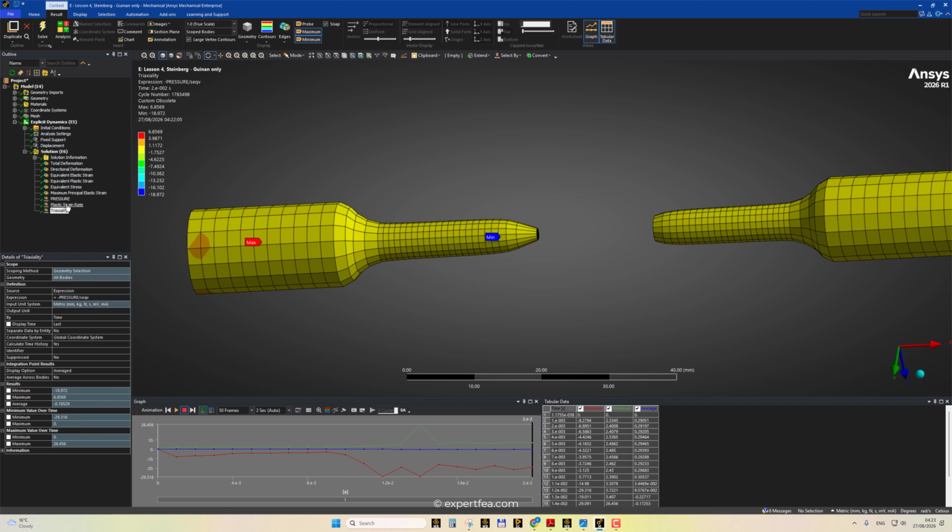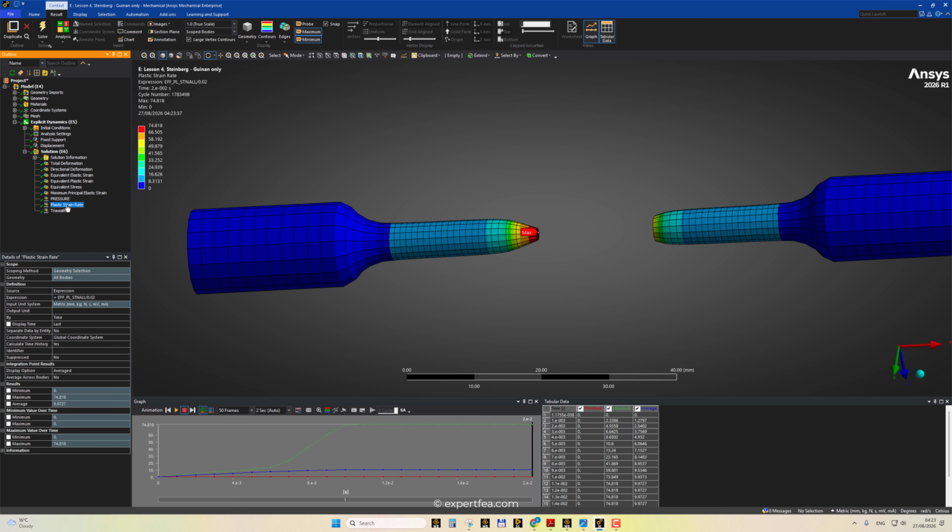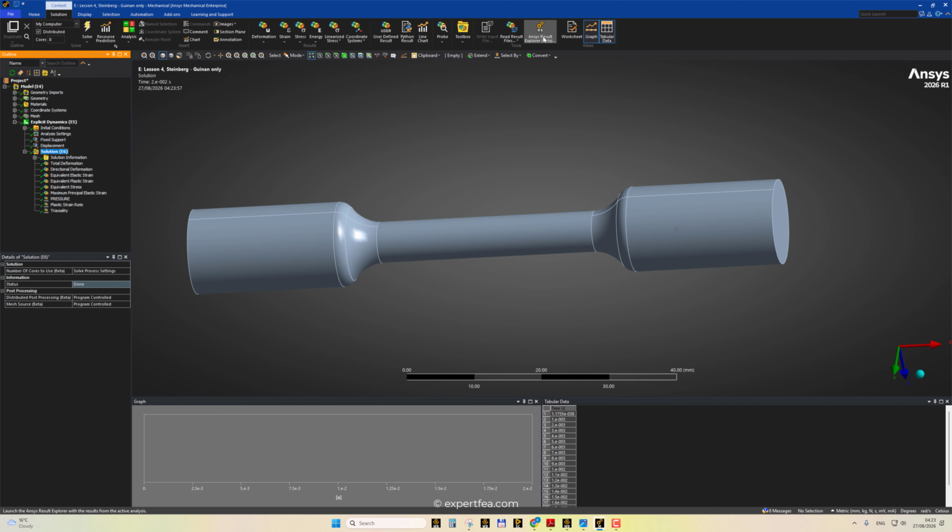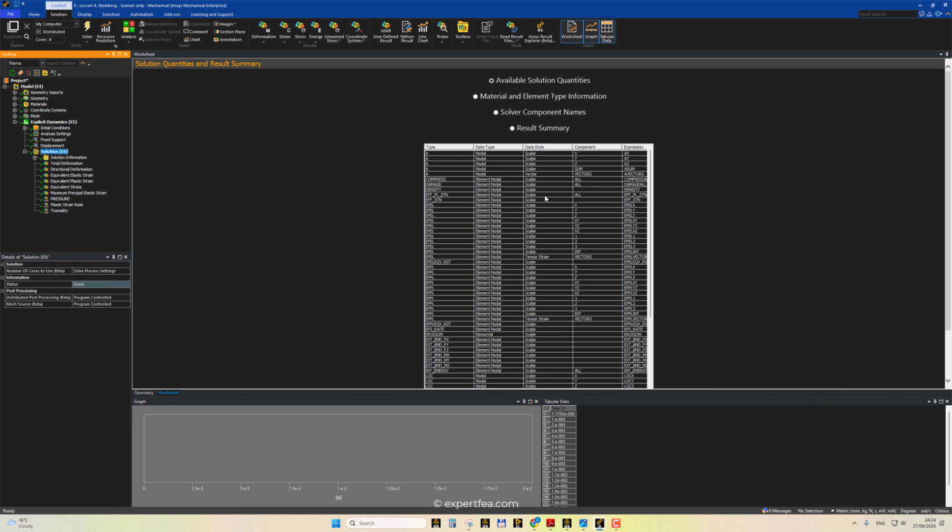I was talking about triaxiality, and now we do see some plastic strain. This is a rate that I calculated, like a speed for the internal deformation. In reality it's effective plastic strain divided by dm times 0.02. This effective plastic strain, you can find it also here in the worksheet.